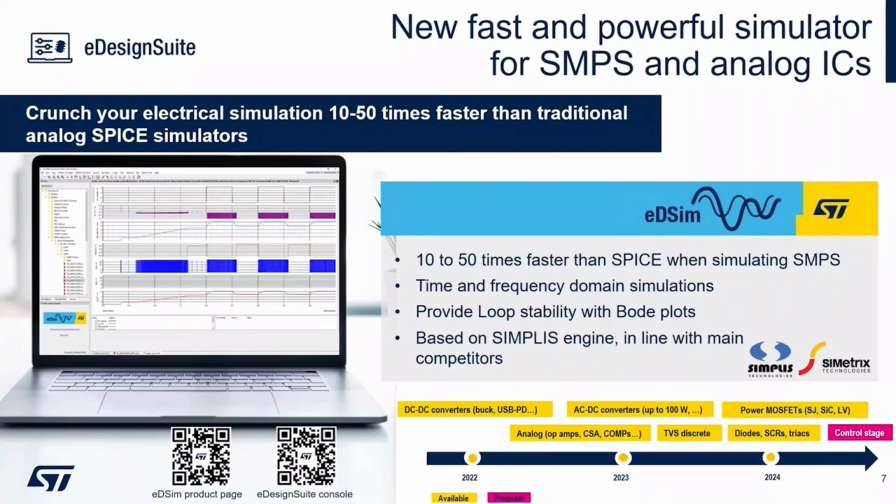This is based on SIMPLIS, which is created by Simplis Technologies. And this tool is 10 to 50 times faster than SPICE simulations for switching mode power supplies. I don't know if you've tried at some point, maybe during school, to simulate a buck regulator using PSPICE. It's painfully slow, and sometimes the simulation does not converge. So that's the reason why we leverage other types of simulation tools for switch mode power supplies.